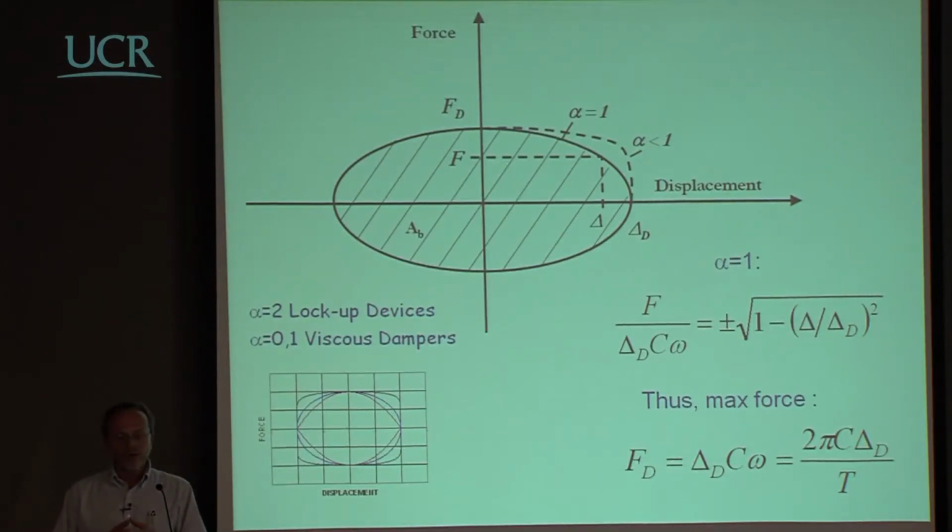But this is not so important. The important thing is, if I give you a structure like this and I ask you, what is the equivalent stiffness? What will you respond? What is the period of vibration? What do you respond? You do not have an equivalent stiffness. You do not know. You are going here, here, here. So that's essentially the problem. But on the other side, the good thing is that you have a large energy dissipation capacity, of course, very large and very stable.